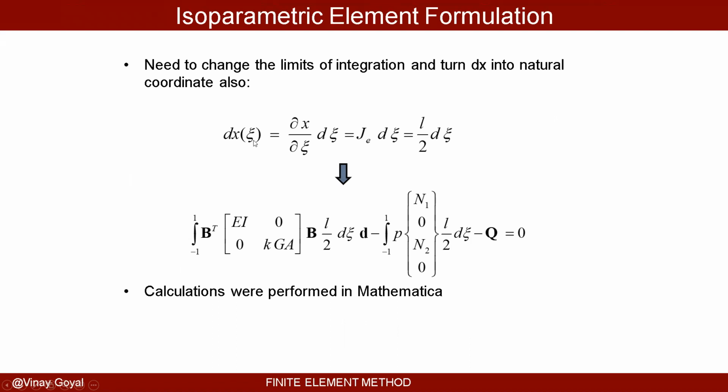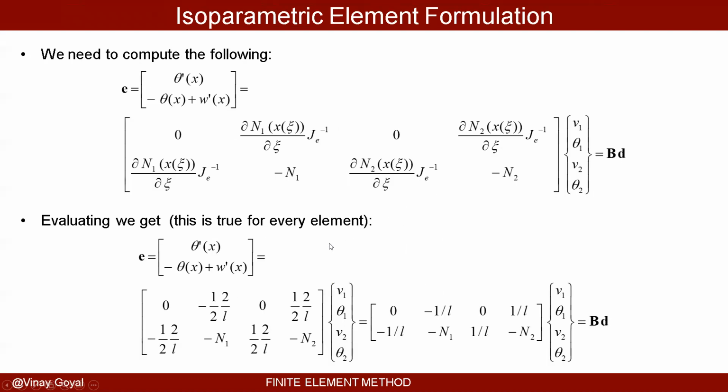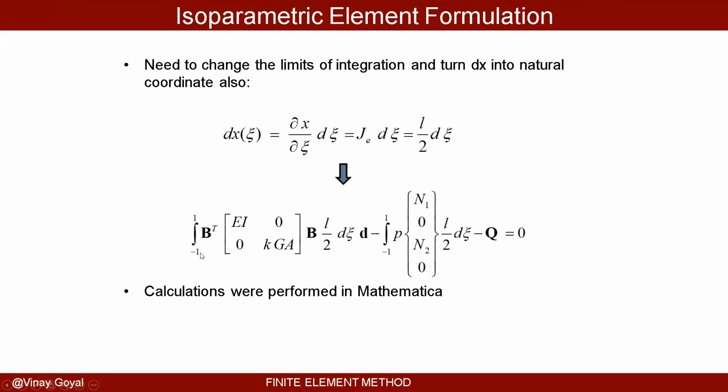And notice how dx can be substituted by L over 2 dC. And B bold remembers this here, which is the same for every element. The integration goes from -1 to 1. The distributed force also goes from -1 to 1, with dx being substituted by L over 2 dC, the Jacobian times dC.